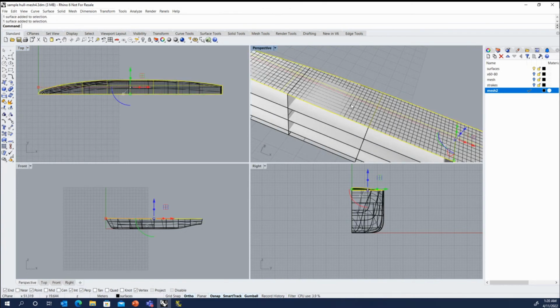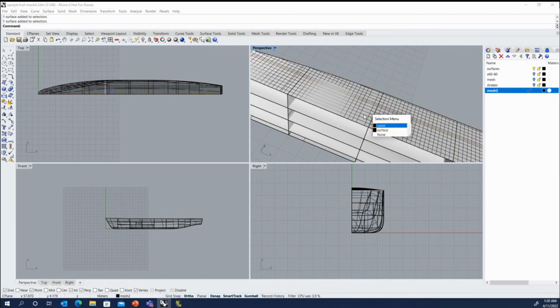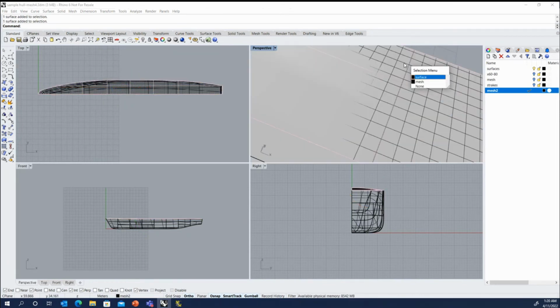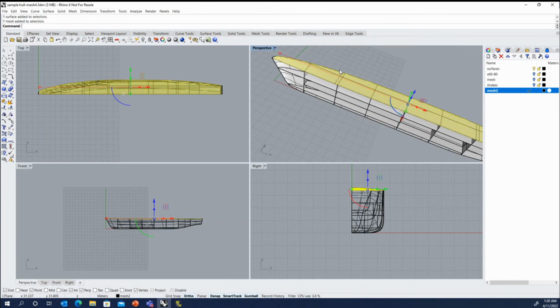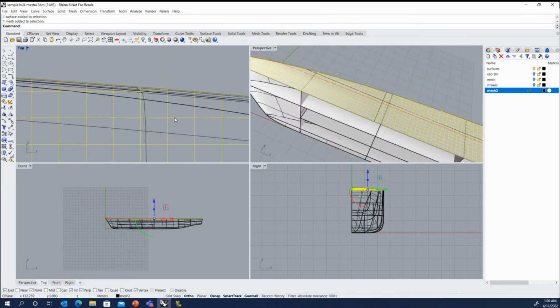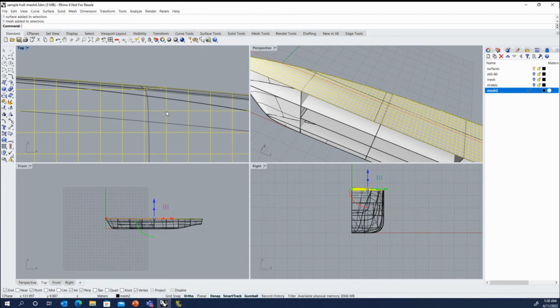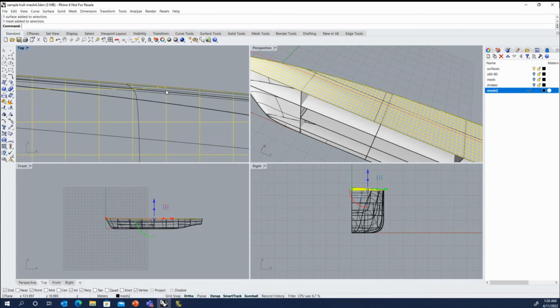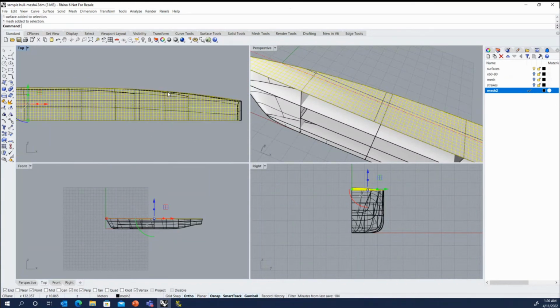And you can see if we click on the mesh, there we go. So there's the mesh that was created. If we look, you can see how some of these lines aren't perfectly parallel to center line. This last segment, this is where that 10% tolerance came in. So we had 1 meter. If it used a 1 meter increment, it would have dropped a point there, but the last little segment was less than 10%. So it added it together and just created a single section there. So that's what the script will do.